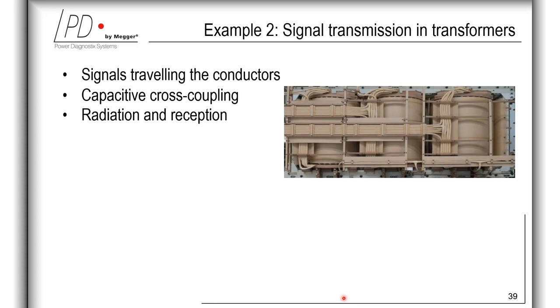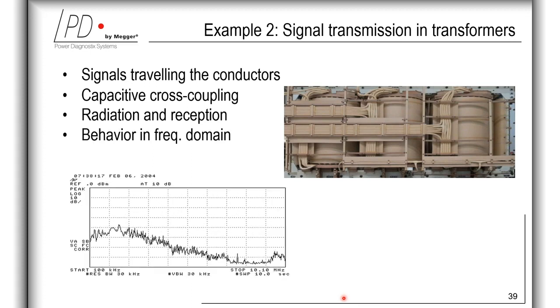Likewise, nearby overhang coils receive parts of the radiated signal, and this leads to cross-coupling. In this way, it can be considered that this effect partially compensates the effect of trapping signals because of the mentioned reflections. In large power transformers, there are many unshielded leads of different coils that are laid and also meet at different places.